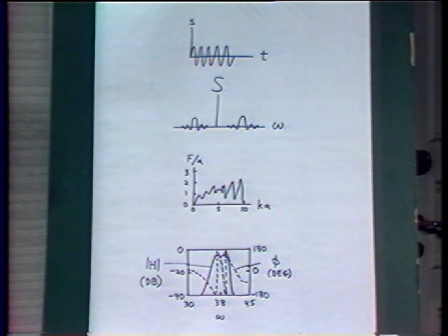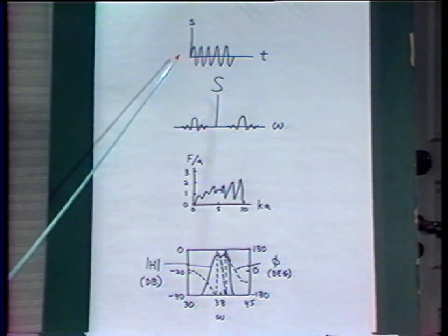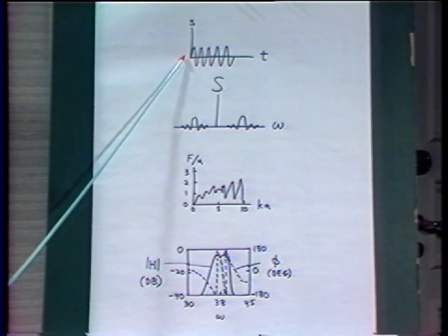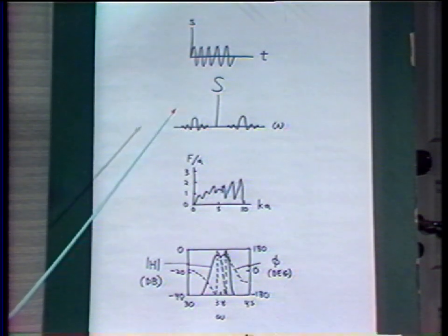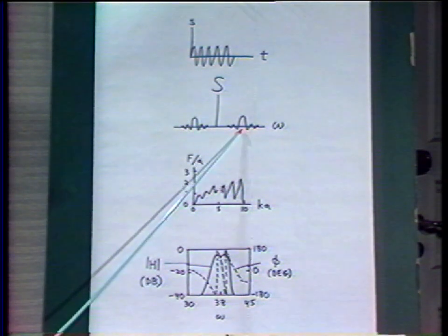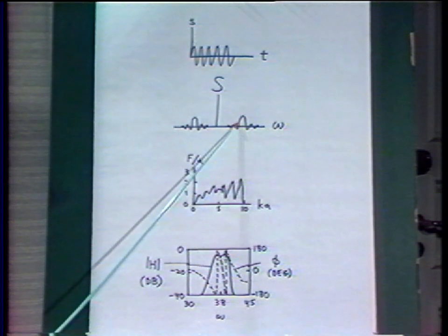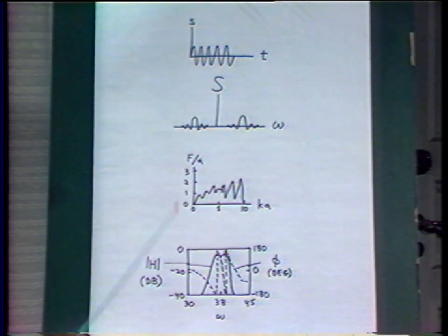These functions are illustrated for some important practical cases. For the common pulsed sinusoidal waveform, the signal spectrum has the characteristic sin x over x form, centered at the carrier frequency, and with a width inversely proportional to the pulse duration.